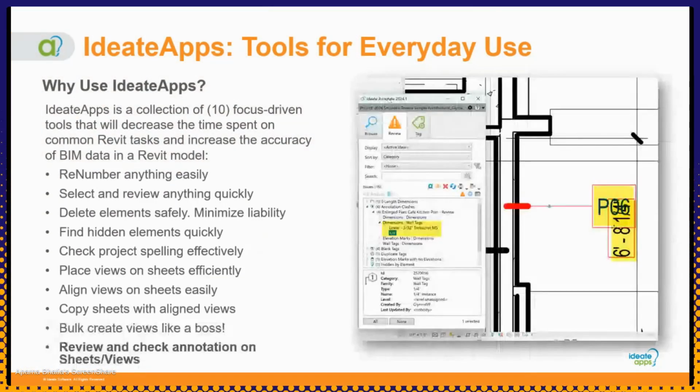So there's a lot to unpack here within this collection, and we don't have time to go into all of it today. So I'll just mention that our construction and structure customers really appreciate the last item listed on this long list, which is the unique ability to document and review annotation clashes within your project. This is not model clash, it's annotation clash, right? So what we're looking at here is a clash between a tag and a dimension. Obviously, that's going to prevent your documents from being successful. So let's take a look at how this works.